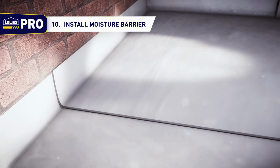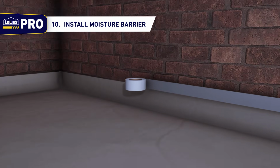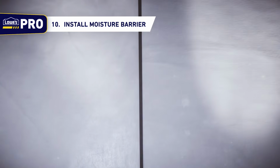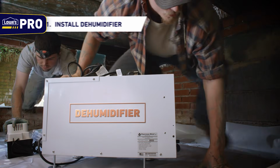Allow the moisture barrier to come up along each wall at least 4 inches above the ground. Tightly tape the moisture barrier to the wall, fold corners, and tape flat. Keep the moisture barrier flat against the ground and overlap each seam by at least 6 inches and seal with tape.